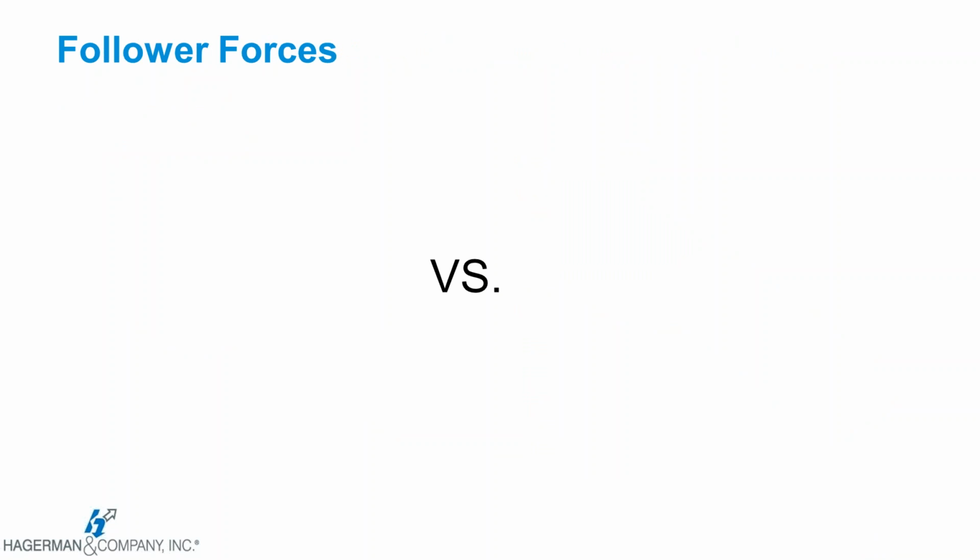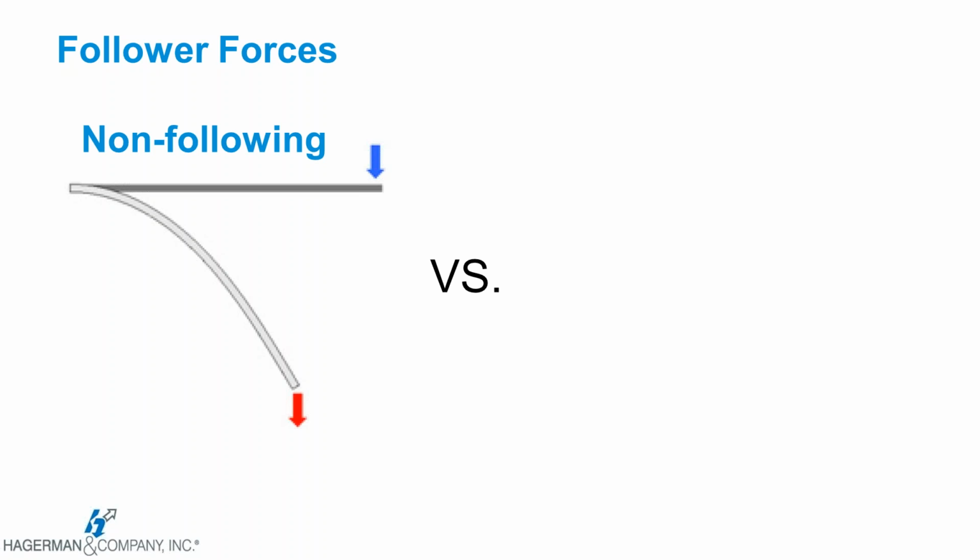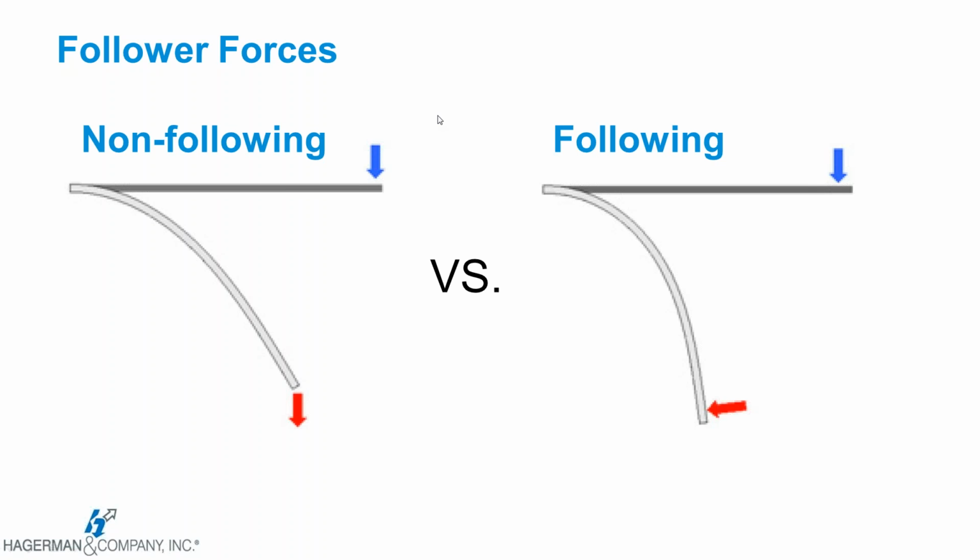So the next aspect of this is follower forces, and what this means is essentially how do the forces on this component function within this object. So in this scenario that I just ran, the downward force that's being applied to that component is assumed to be a constant downward force. In this scenario, with a true follower force, that direction of that force may change along the path of the deformation of our component. So, not only staying in contact with that face, but also always pushing towards the direction of the normal of that face.